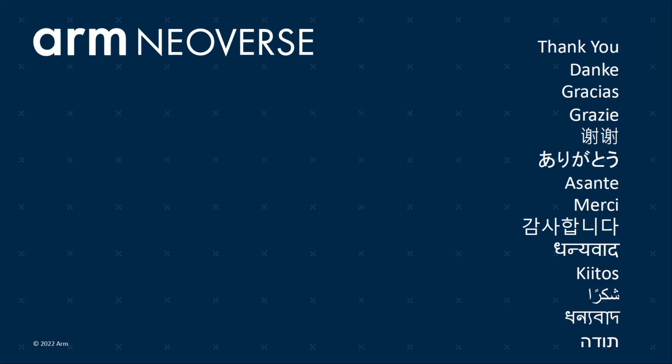The silicons usually have a vector engine. Each CPU has it. So, for example, in Intel terminology that everybody is more familiar with, it is AVX512. ARM has an equivalent version of that, which is called Neon or SVE. And this RAL is using these vector accelerators. So the idea is not to use any external accelerator, just the plain CPU and its own vector engine to expedite these loads. We have even written LDPC and turbo encoder decoders on that, which is good for small throughput, like below 1 gigabit per second, etc. We can get into more details if you want later, but it has a use case.